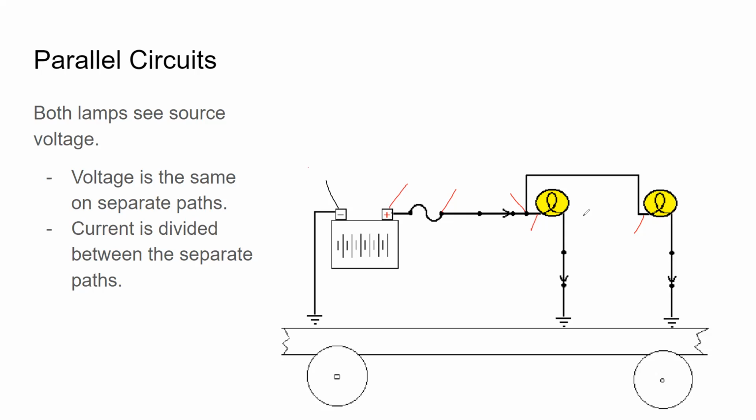When we need high current for a circuit, we have to increase the size of the wire. So very small bulbs in our car, like the light bulbs that light up our dashboard, can get by with a really small wire because they don't need much current. Great big bulbs like our headlights need a little bit larger wire because they require more current. The starter motor that gets the gas engine running requires a huge amount of current compared to anything else, so it gets the biggest wires in the car. They're known as battery cables.